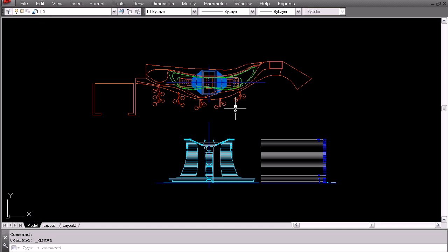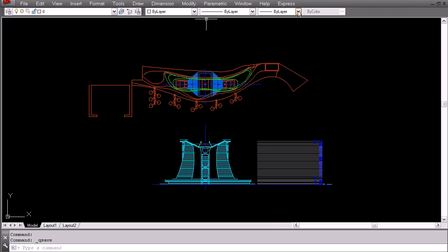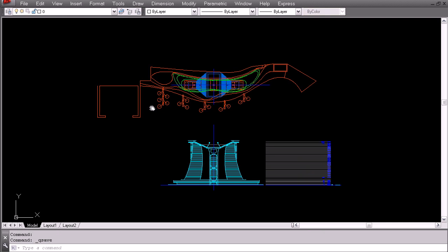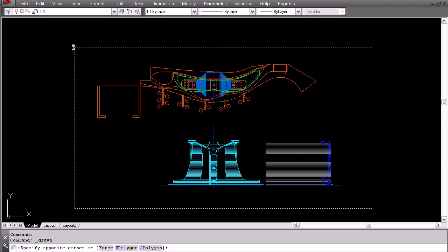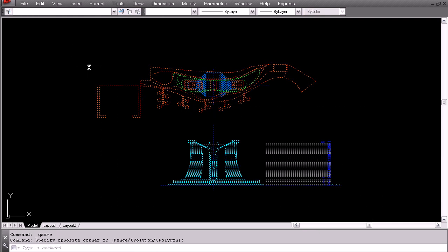So the first thing we want to do is make sure that you bring the building into the right place on your set of drawings. Now what we can do is start by copying and pressing Ctrl-Shift-C, and then we can click on a base point that we know is the same in the existing set of drawings. Fortunately here we have this little pier that we can use this corner of, and we're going to use that as our base point. So we click on that corner right there.